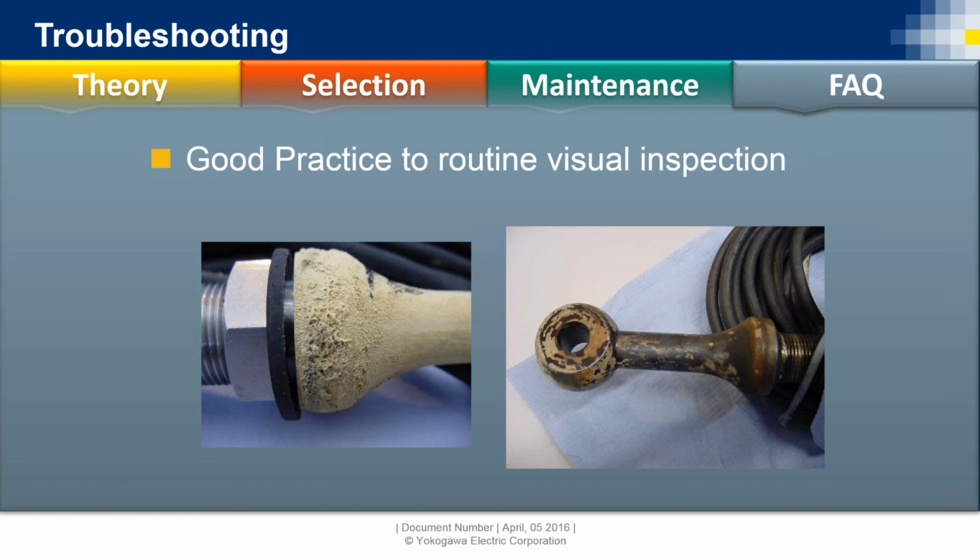Here's another one. Be cautious of those inductive sensors. Literally, you can put one of those inductive or electrodeless sensors in line and it will last probably years. But they do fail over time, so it's good practice just to visually pull it and check it. I don't know how frequently people do it, but I would say probably a minimum of once a year, or you may have standard procedures that when the line goes down, go check it just in case, because they do give way.